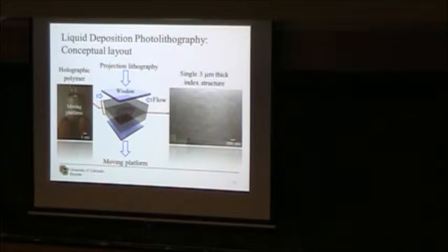In contrast with the volume holography though, I'm not going to thermally cure one of the monomers. I'm going to leave them both initially liquid. And that's important because how I'm going to build the three-dimensional volume in my chamber here is by repetitively flowing that in and repetitively patterning it, and repetitively layering it, building my three-dimensional volume layer by layer.